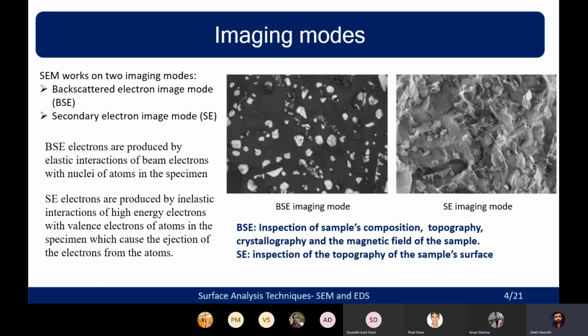So I can tell you one example in my case. I have a sample in which we performed laser color marking, and for that color marking we heat the sample surface with lasers. So during the process thin oxide films are formed on the surface. For analyzing those thin oxide films, we have to cut the sample in cross section and then see in the perpendicular direction.